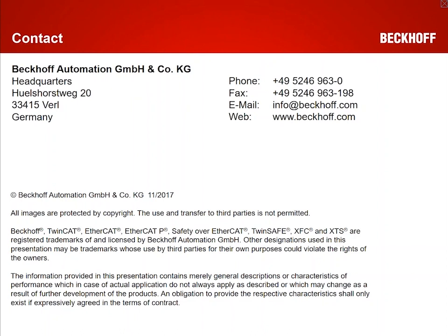We can only show those signals that are provided in the C code by a variable. Sometimes the Simulink coder optimizes the code in that way that the signal is not represented anymore as a variable. And then we cannot show this signal in the block diagram.